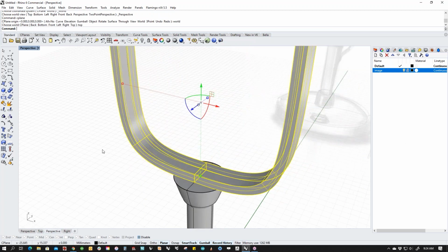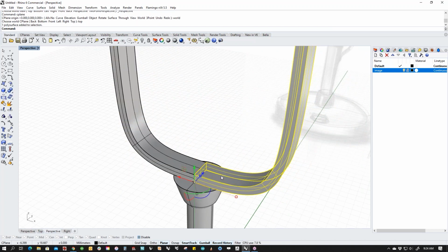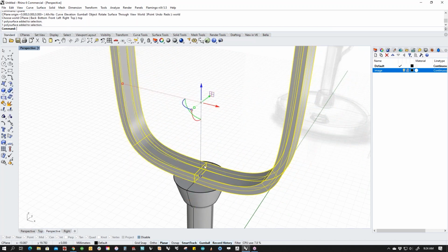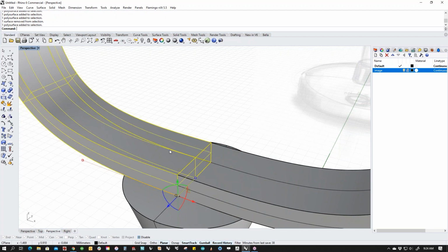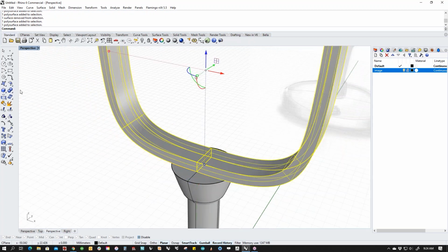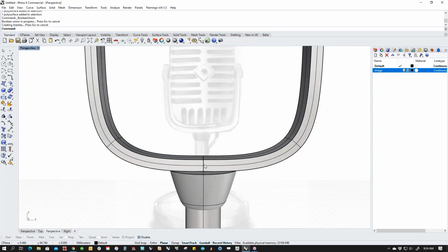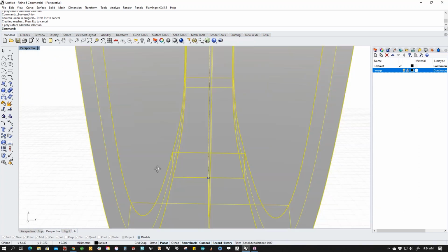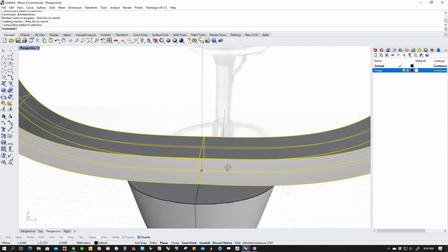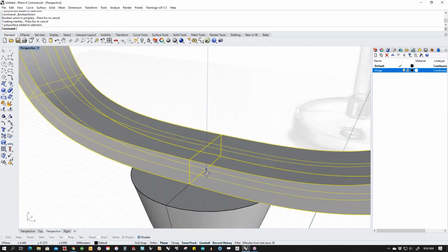And in this case, I want to show you a power that V6 has that V5 used to struggle with, which is coplanar booleans. In this case, this plane right in the center, this one, is exactly coplanar with the one on the other side. And I guess I should try it first before I shoot my mouth off. But V5 used to fail very often in that situation, whereas V6 tends to handle that a lot better. So that's a good thing right there.